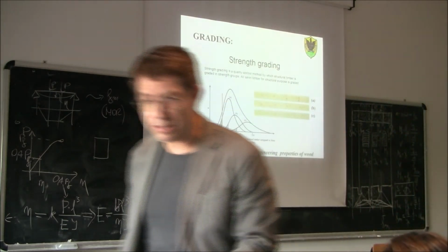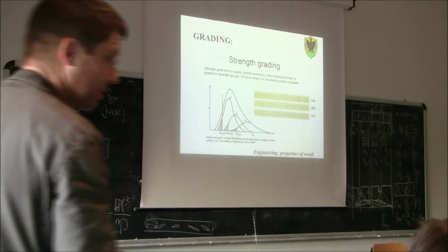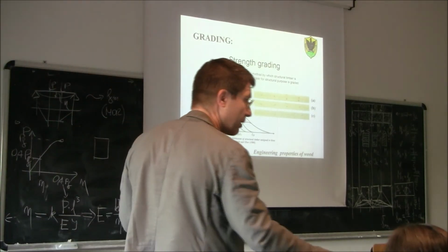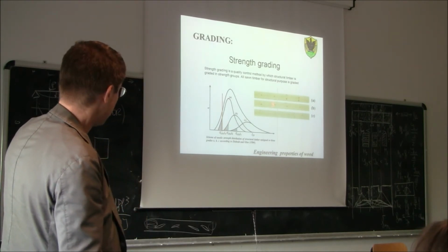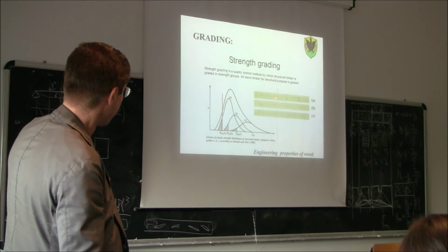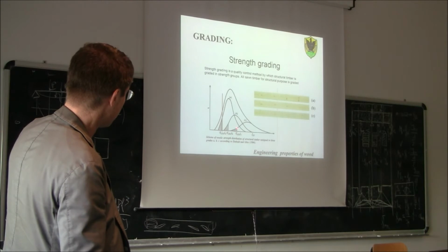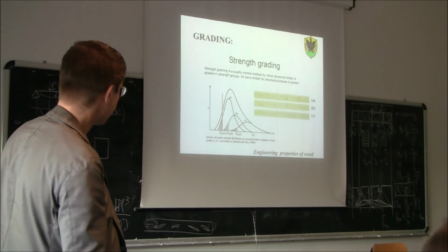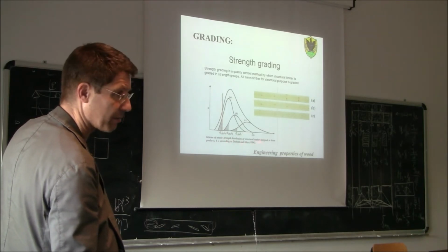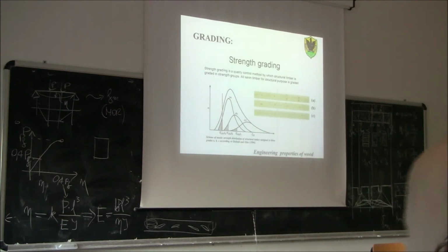So the logarithm of the strength is normally distributed. This is a kind of distribution if you use 14 or maybe 13. But this is not important anyway. Important is to see that, as soon as you move from few big knots to more lower diameter knots, you see that the curve moves towards right, which means that the characteristic strength is basically increasing. Clear? Good.